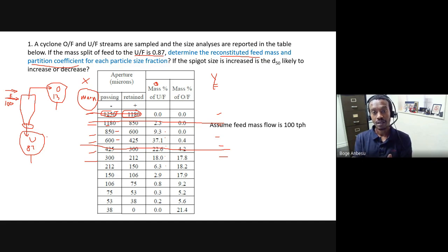So this is already a dense media containing particles, and your water shouldn't be worse than that. But when we use dense medium separation, we try to separate coarse particles from one another. There's no point in preparing a dense media made from 75 micron particles if at the same time you want to separate 20 micron particles from one another. It doesn't work like that.